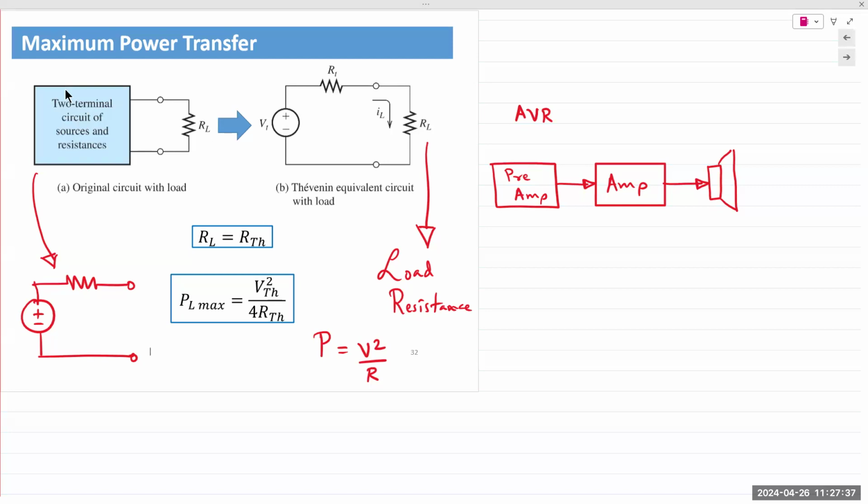But that is not the point where you get maximum power or maximum speed. In order to get more power or more speed, you would burn more fuel. Burning more fuel would be inefficient, but you would get higher power and higher speed. Make sense? Same thing with electrical circuits. Maximum power does not translate to maximum efficiency.